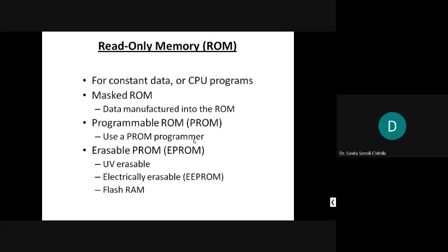You put the memory in the programmer, and you can program it, like you can send the zeros and ones from your developing system to the target board, like how you are doing it in the VHDL lab. The target board is an FPGA or CPLD kit.